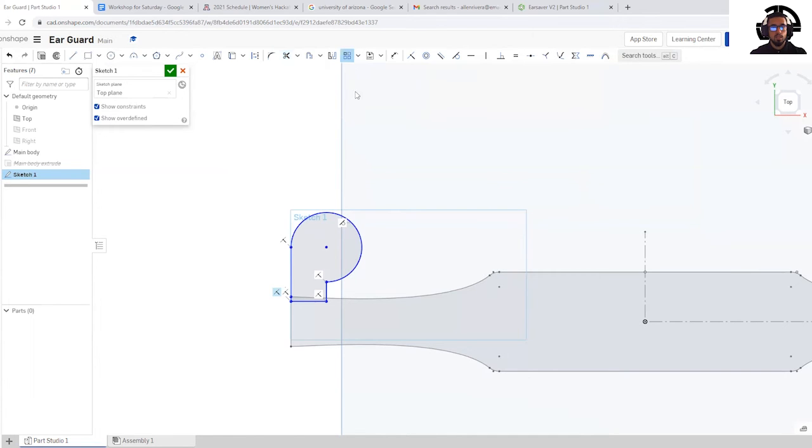Now, what this does is it allows me to select this portion of it and enable me to make a pattern of this. Sorry, just give me 1 second. Recording. Okay, so now we have 3 times because it created a pattern. So we have three new of the same object in line as well. They're all equidistant to each other, and they're all set to be linear.